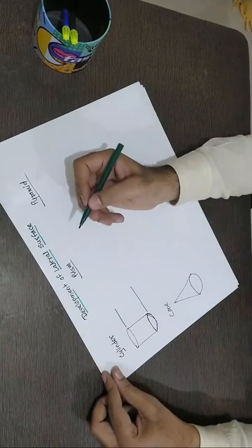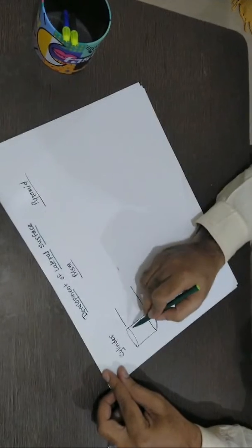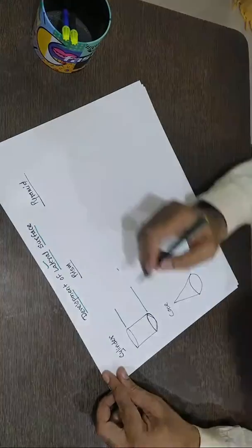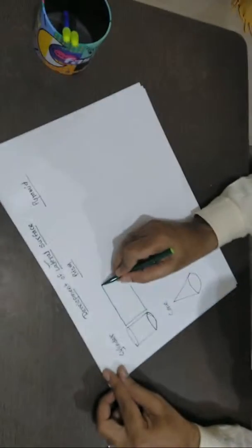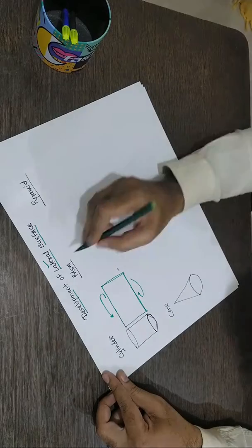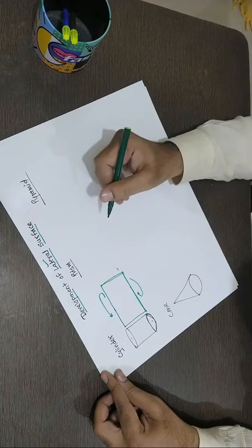What is the meaning of this development of lateral surface? Lateral means in the lateral direction. Suppose on this cylinder, if I wound one cloth or a paper, its unwinding shape is a development. So we are interested only in the lateral surface. Very simple. This cylinder can be obtained by just rolling this paper in this way. Technically, in graphics language we call only this the lateral surface, meaning we are not interested in the top and the bottom face of any solid.